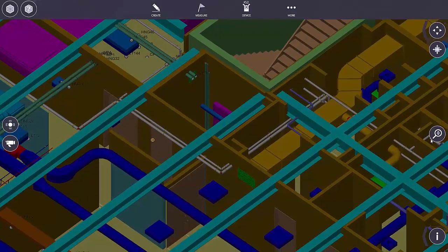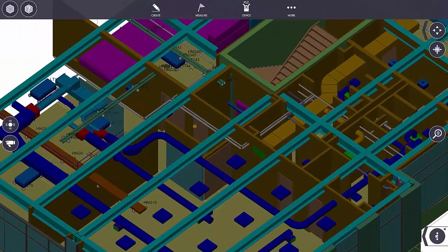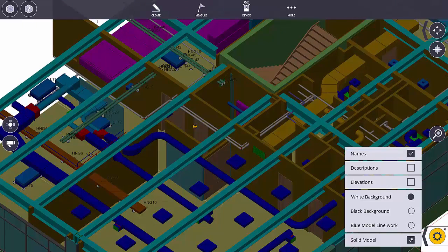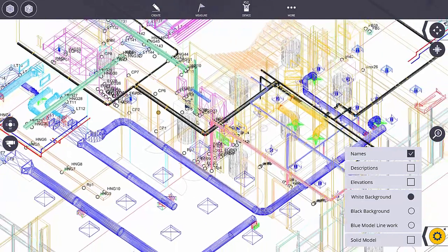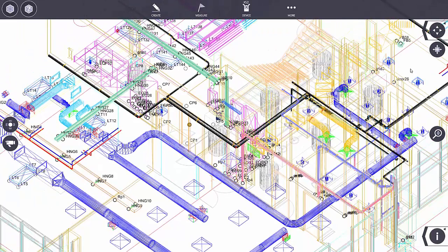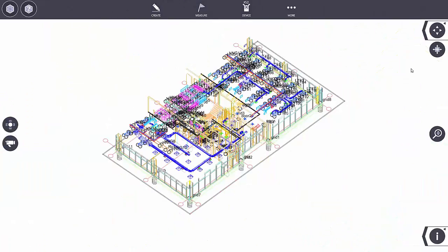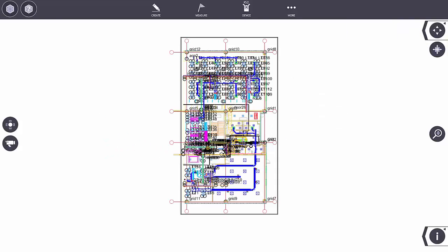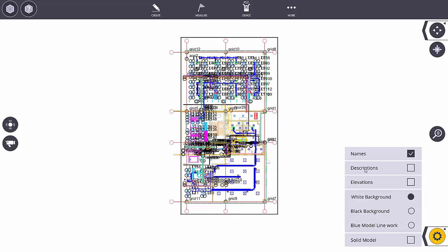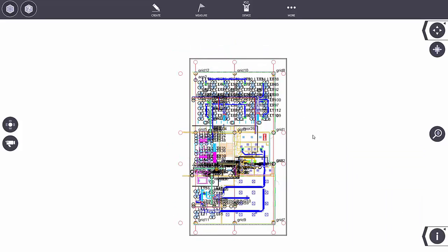Once I'm done looking in model view, in solid view, I can always get back to my zipper and turn solid off, and then it turns into wireframe. That can be a little bit daunting looking at wireframe here. So one of the things that we can do is get up to this zipper. This is zoom extents, but if we pull this out, we can go back to a specific isometric view if we choose, or just simply go back to a top-down view. So just kind of showing you what options you have with the zippers, and a little bit more about some layers as well as some visibility of the model and the points that are in your job file.